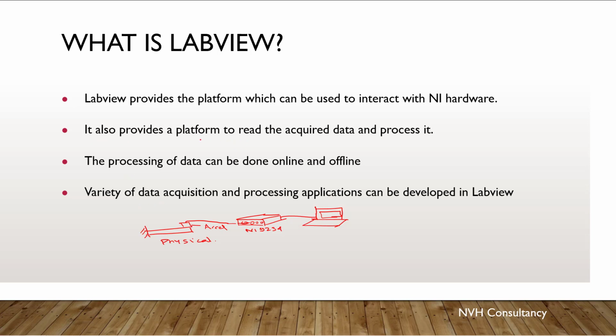Again, it acts like a platform to read the acquired data and process it. Okay, so the whole data that is acquired is basically first of all converted from the physical domain to the electrical signal via the accelerometer. Okay, now this is then converted to your digital format via this NI9234 device.